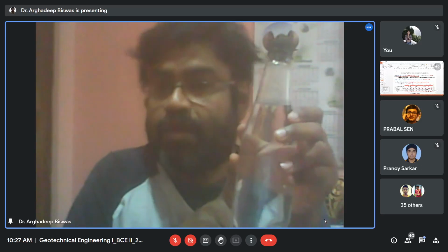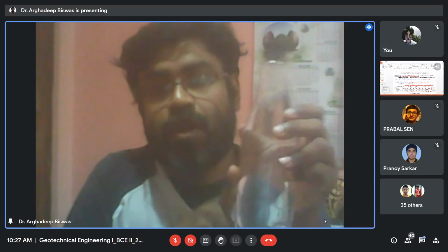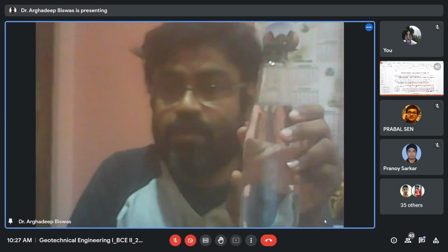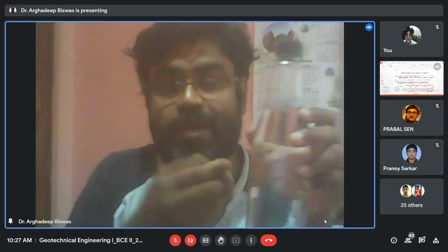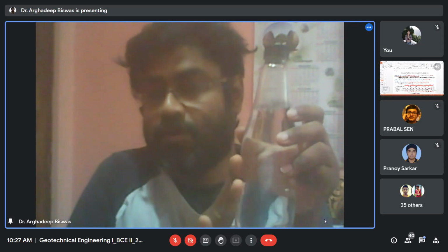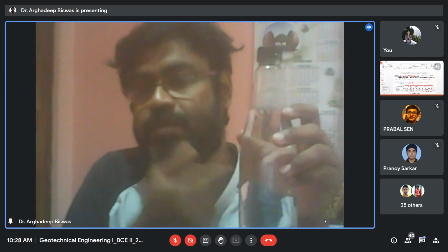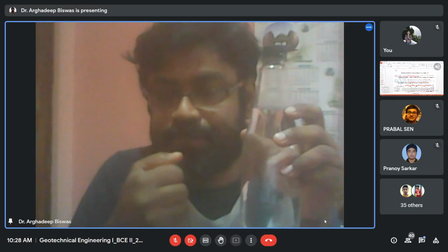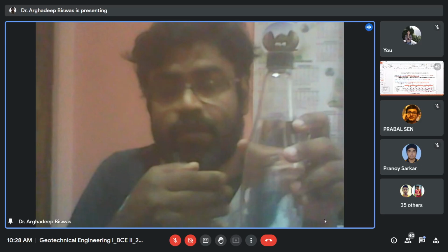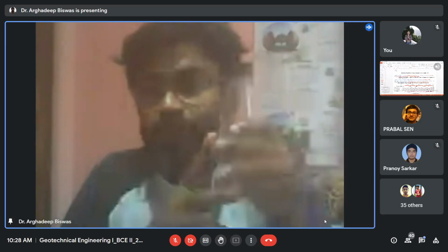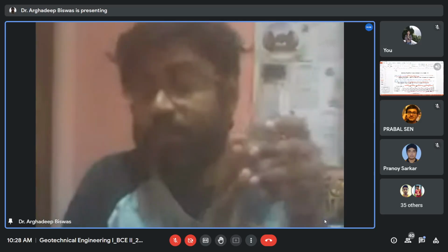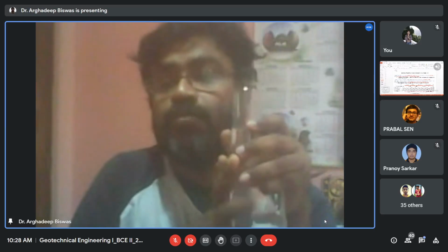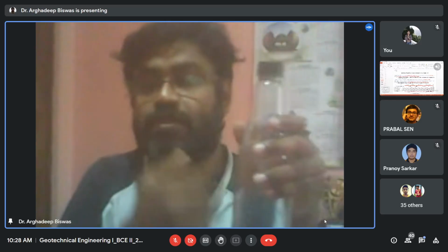Now, if that is true, then you can say the soil water mix remains saturated. Right? Because I am just extracting the water, I am not extracting the soil body or solid particles. And the water I am extracting is the water which was in excess of the minimum void space. So the volume change is due to the reduction in water content only. Total volume change will be equal to the volume change of water. Now you are extracting the water.